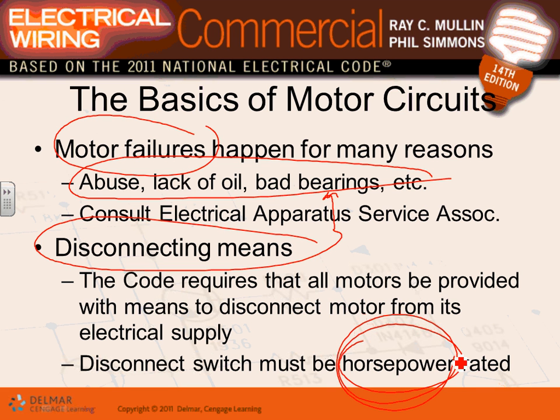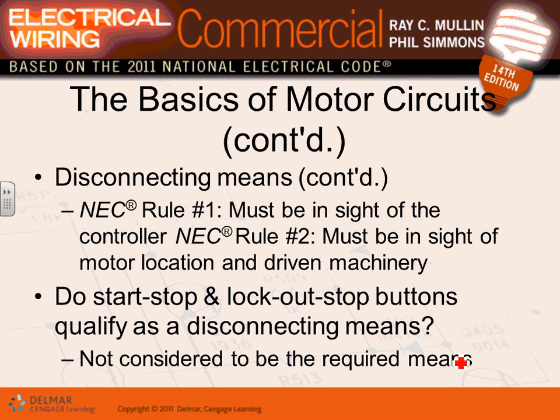Any comments, guys, about horsepower rated equipment and disconnects? When we size the disconnects, you have to be aware that disconnects have to be amp as well as horsepower rated for motors.